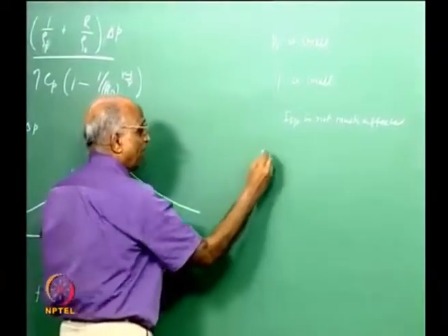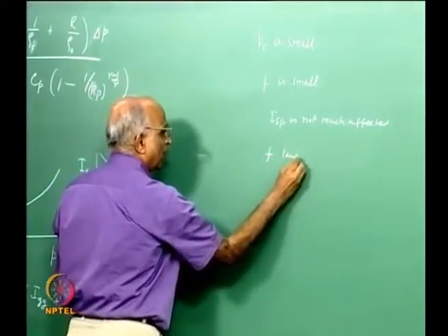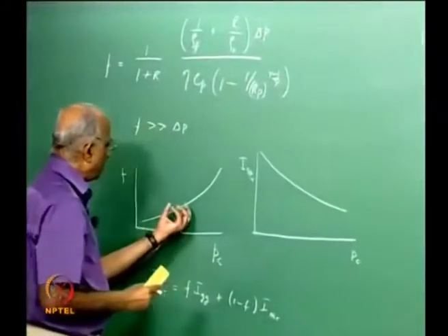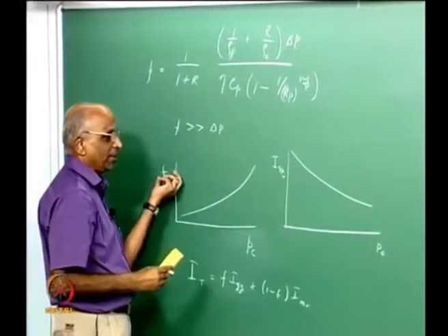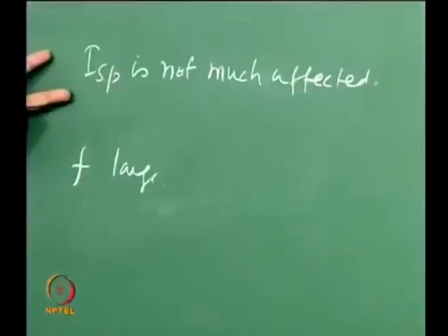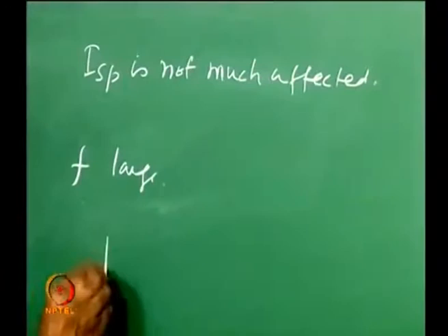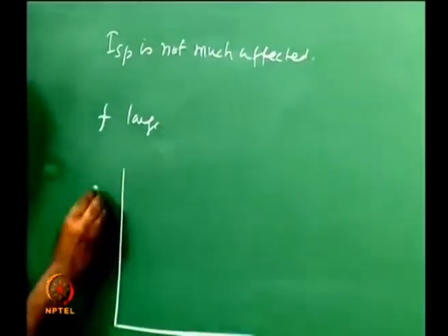Whereas if F is going to be large, I am unnecessarily pumping so much fuel into the gas generator that my net ISP comes down.